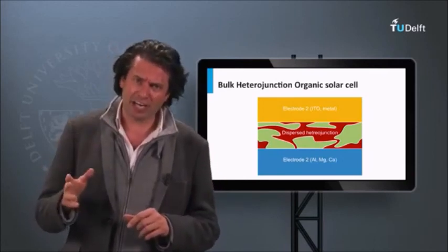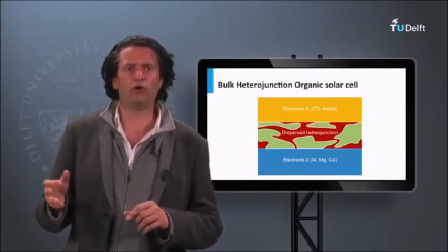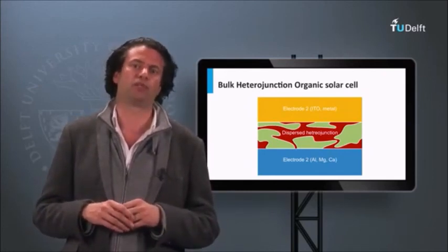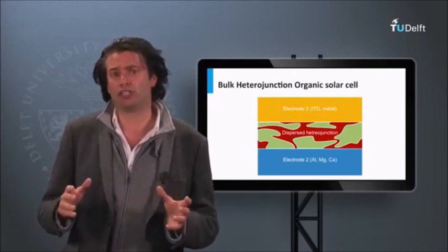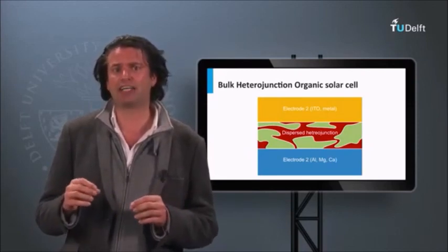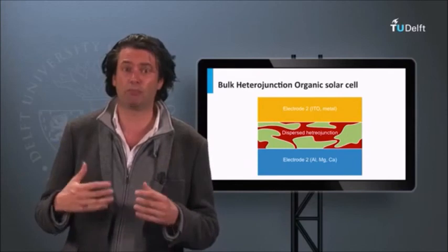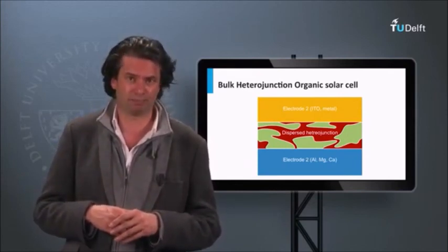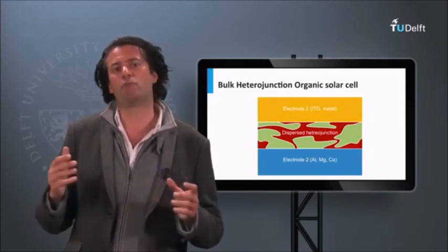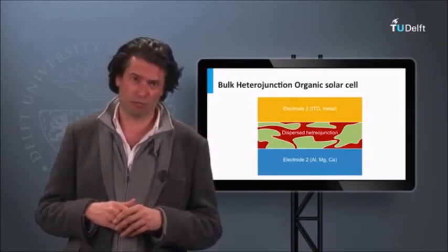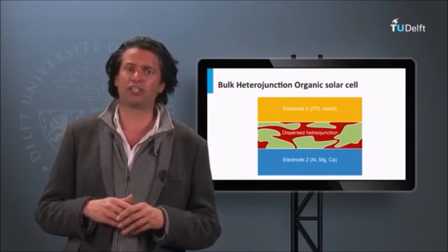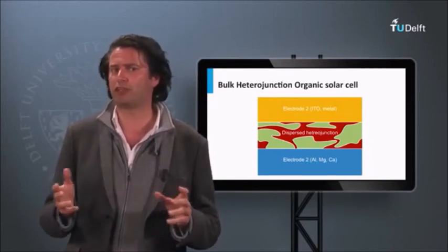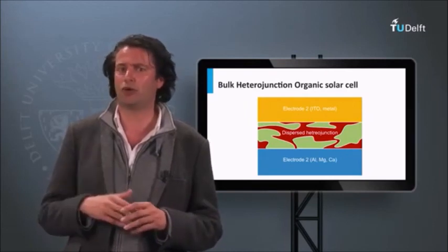Important disadvantages are a low efficiency, a low stability and a low strength compared to inorganic PV cells. Although organic solar cells can be made cheaply, the need for highly expensive encapsulation materials to stabilize the organic PV products limits the industrial application. To my knowledge, no company is producing organic solar cells at the moment. Konarka Technologies has been active in the past. The small modules had efficiencies in the range of 3 up to 5% and lasted only a couple of years.